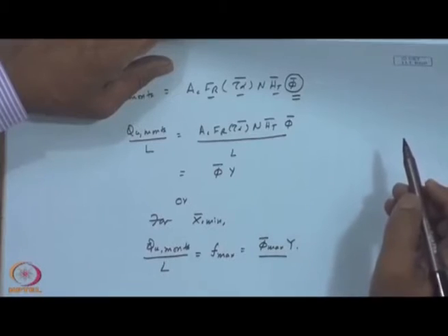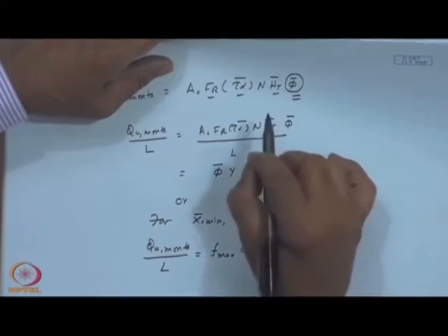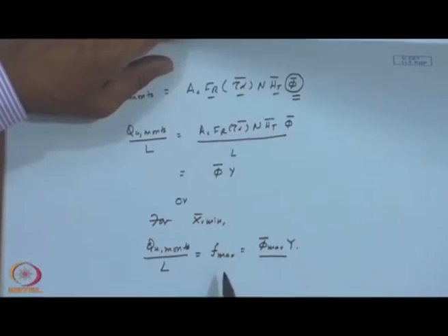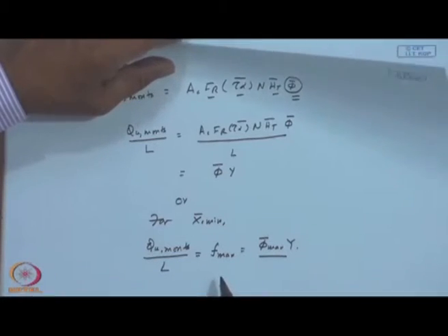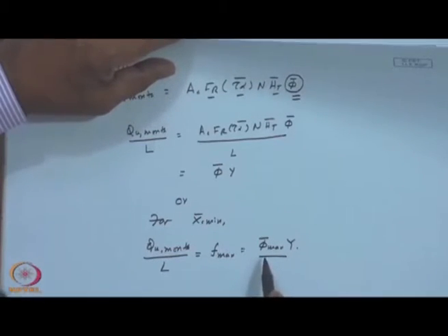If all the energy delivered by the solar collector is going to meet the load, there are no losses on the pipelines, there are no losses in the heat exchanger or in the tank, then this will be the solar load fraction that will be met. So, in one sense, simple knowledge of utilizability can give you an estimate of what is a possible solar load fraction maximum. This is almost an ideal way of a number that one gets.